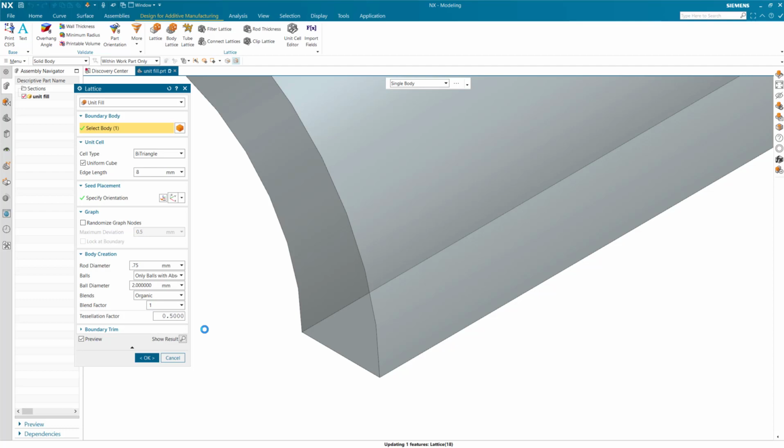Now, you may want that for something such as in the medical industry. That all depends on what your particular design intent is, what machines you have, what material you're using. There's a lot of factors that come into play when you're deciding what lattice you use. Maybe you're using it for cushion. Maybe you're just using a lattice for lightweight. Or maybe you're even using it just for looks. So you have many different factors that come into play when you're selecting these lattices.